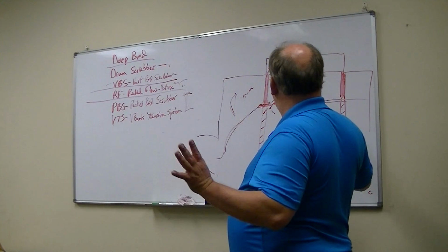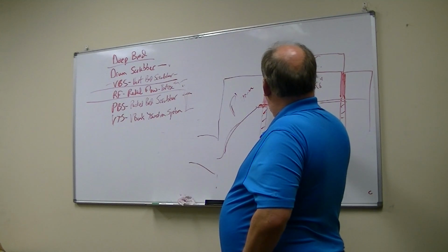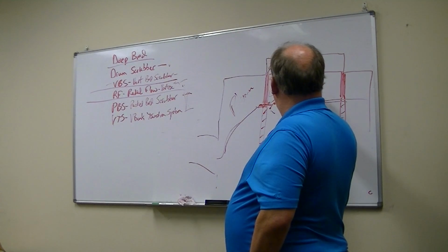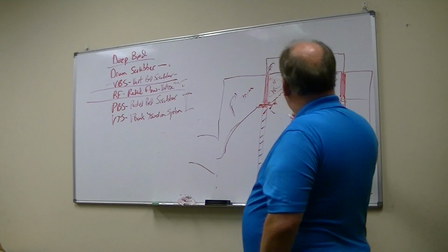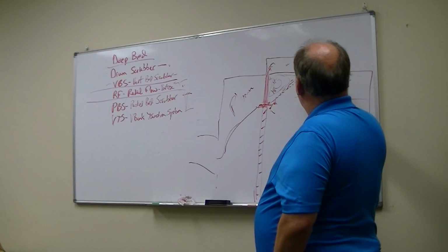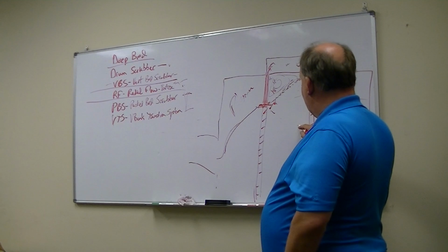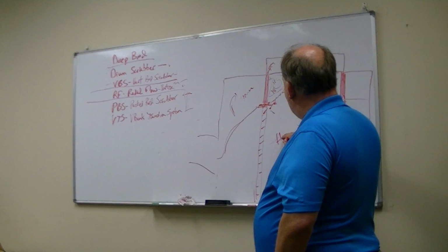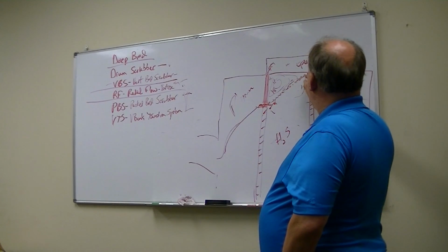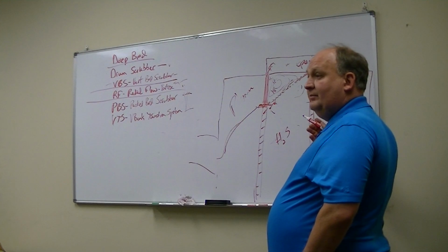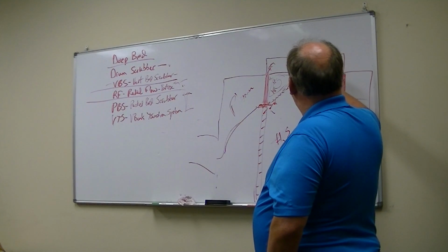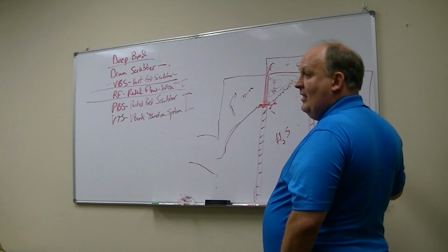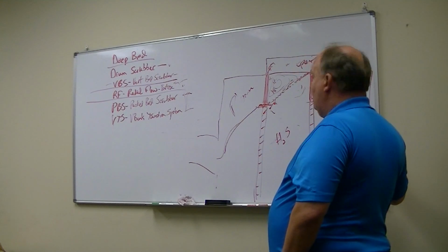So you're going to get no usage of this media here at all, and you're going to get some usage of this media. Now, here's the problem: this air starts to come out. So it travels through this bed of adsorbent media. So if this is for H2S, then it travels through and it takes all the H2S out of it and it does a good job, okay? But what happens when it gets here? Well, now I can just jump over and head back down. So it's doing some leaking in that case.